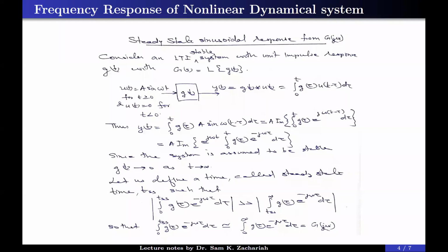No, sir, about the saturation of the integrator. Yeah, integrator, sorry. Okay, what I was telling is, say, integrator. First, I explained the physical implementation of integrator. It is normally implemented in electronic circuit as a capacitor in the feedback path of an operational amplifier. And the integration will be stopped if the output of the op-amp is going towards saturation. So we have to stop the process of integration itself. That's why I defined it as an embedded limit within the integrator.